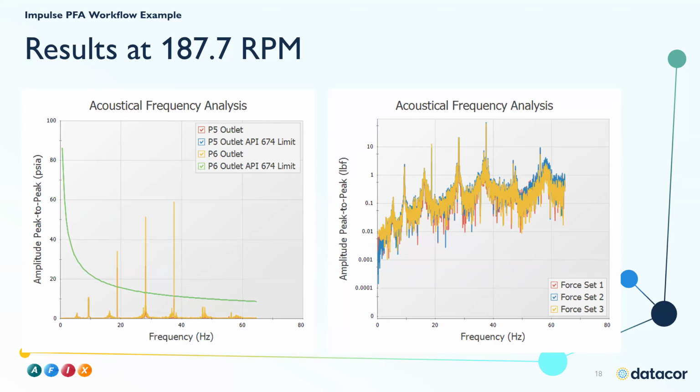So if this was a real analysis, it would be a good time for us to adjust that sectioning resolution. We would certainly want to increase it. We could stand to have higher runtime here. We could also use the unsteady Bernoulli friction model for the transient friction model, or we can use the DGCM cavitation model or some combination of those steps. All of those would clean up some of this noise and make it more realistic.